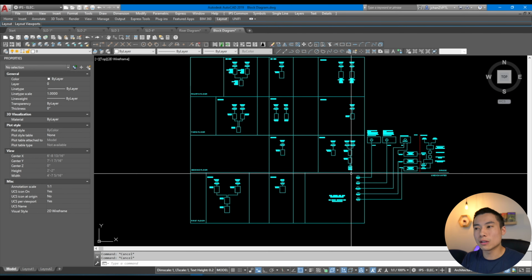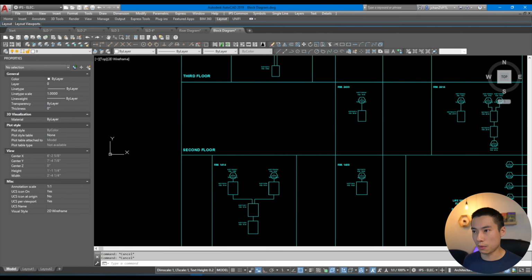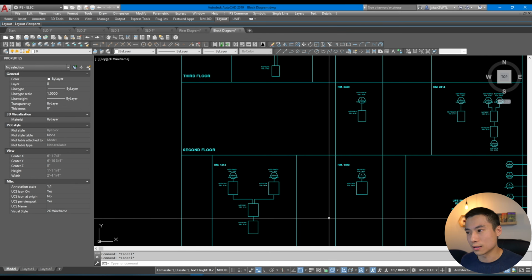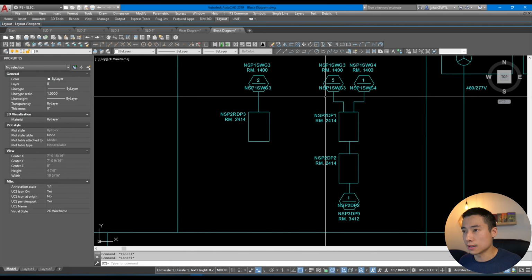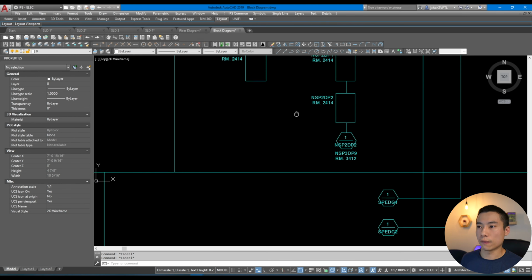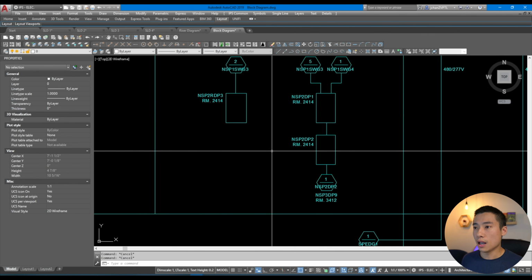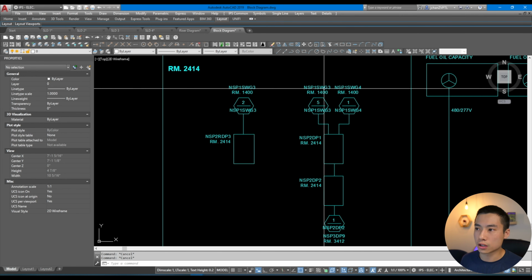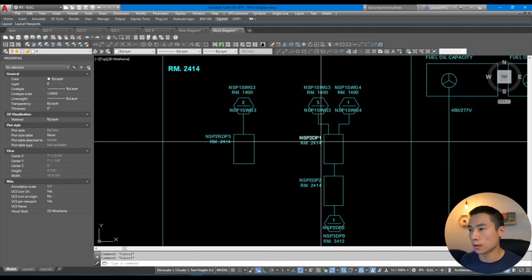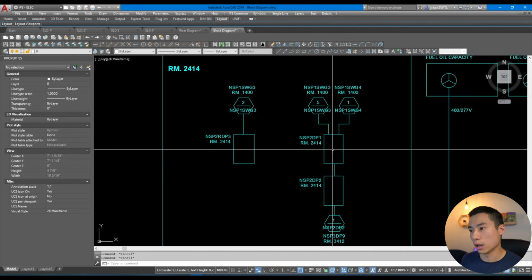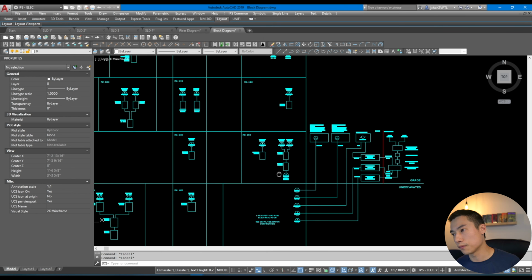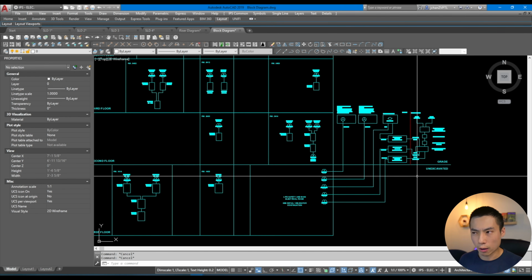So, you know, gives you a little bit of an idea of how the whole system is arranged. And then we have these random spaces that are kind of like out in the west side of the building. We couldn't really stack them, so that's just where it is. So the detail level for this is that you just reference. So like here references this block diagram, and it says like it goes to, I don't know, this one here has 2 feeders. So 2 feeders coming from the switchgear 3 and switchgear 4 going to this distribution panel 1. And then, you know, it just keeps feeding down. So a block diagram is easy for someone that's not electrically savvy to follow along a little bit better.